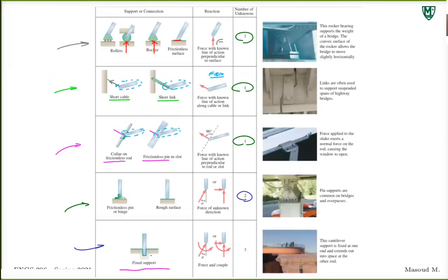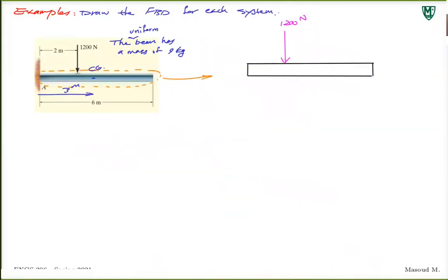I have to take into account two components of a force and a moment. Now, you might ask which direction you put it at this point. It doesn't matter. It has to prevent motion, so you might think, are we preventing the motion to the right or to the left? Don't worry about that at this point. Just take those forces into account. So we have one in this direction, one in this direction. For the sake of argument, I'm going to take this one upward and this one in this direction. So that would be F in Y direction, and let's just call this F in X direction.